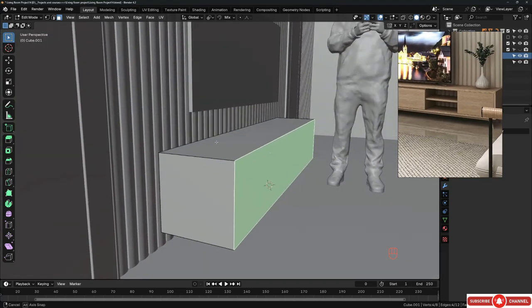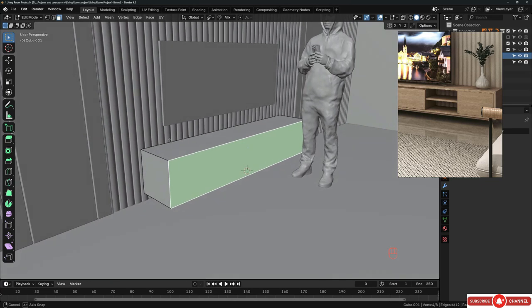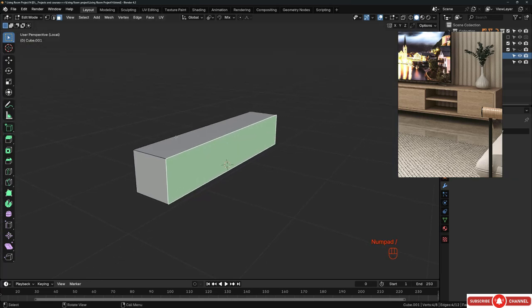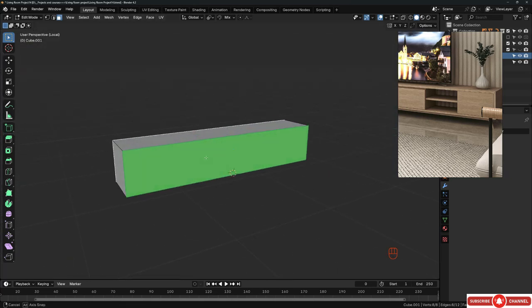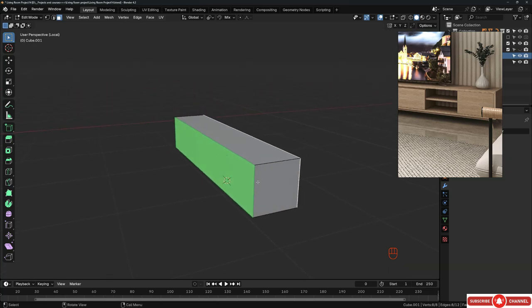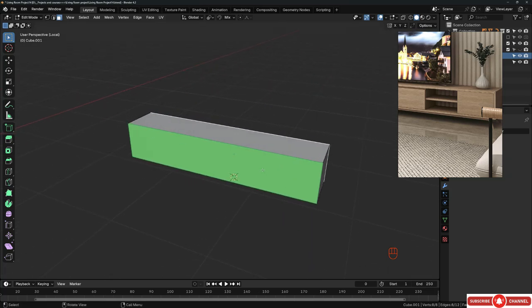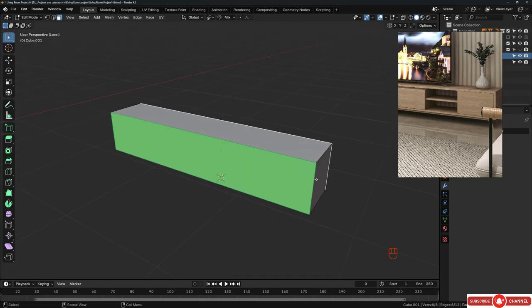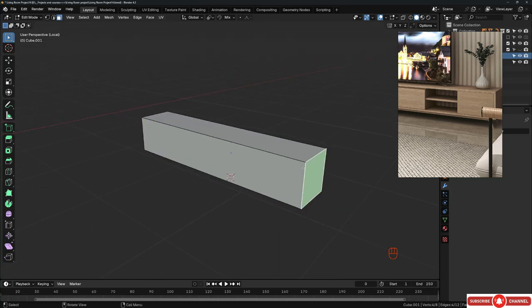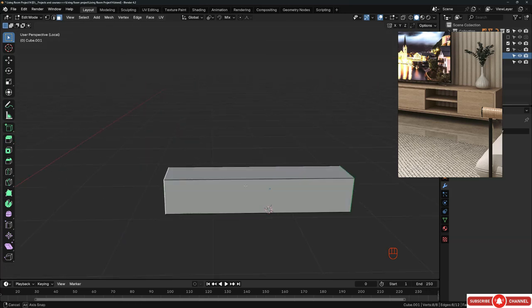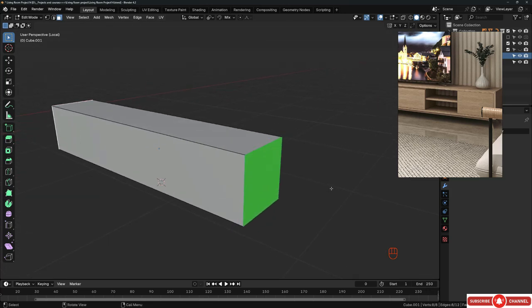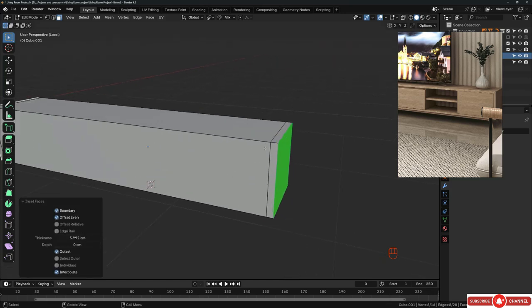All right, I will select this face and I will go to the local mode, hit slash, and I will select this face as well, and I will give it an inset. You can give it an inset right here, or you can do something else, like grabbing these faces like this, and hit I to make an inset, and then hit O to invert the inset so we can have edges like that. And after that, you can determine the distance after doing this.